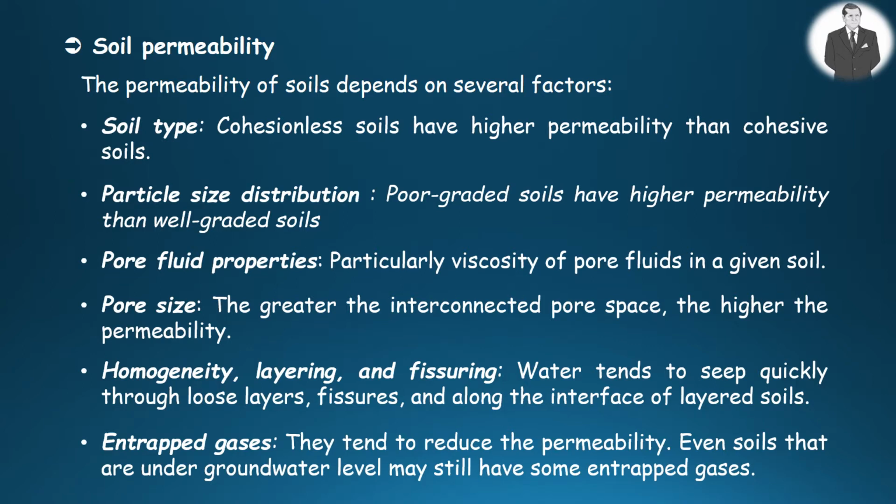When the viscosity of pore fluids in a given soil increases, then the permeability decreases. The greater the interconnected voids, the higher the permeability. Water tends to seep quickly through loose layers, fissures, and along the interface of layered soils. Entrapped gases tend to reduce the permeability. Even soils that are under groundwater may still have some entrapped gases.